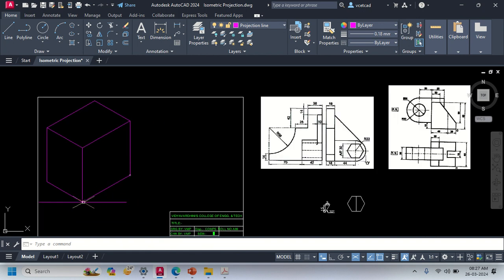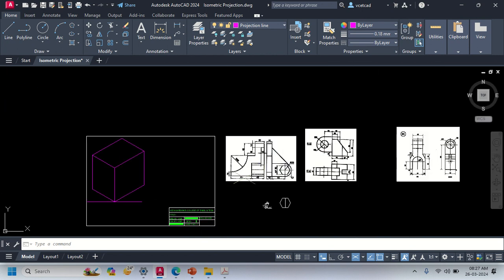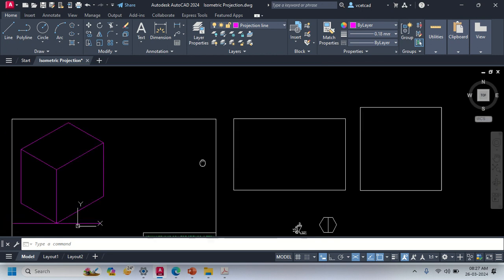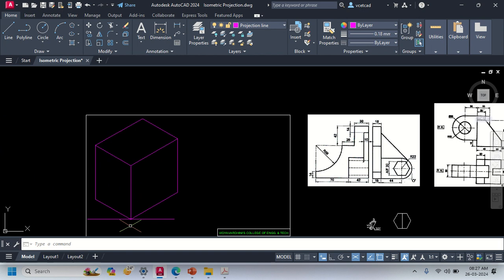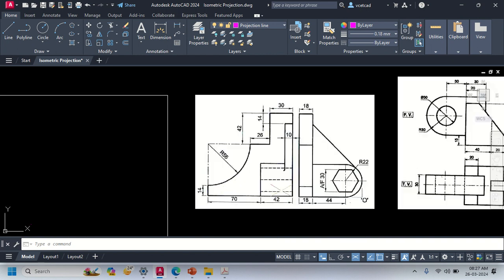Okay, so what we have done, we have calculated this considering it as a front view. So the origin is at this side. So this is the side view of the given question. So here you will get the origin if it is the side view. This is the front view. Length is 112, height is 112, and width is 84, right? Now, in such type of question, we have to start from the rear side because the rear plate is flat. So let us concentrate on the rear portion, right?